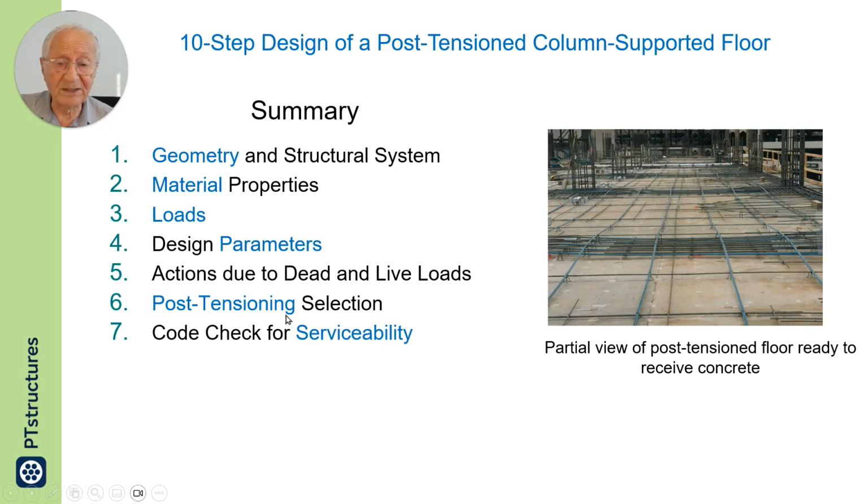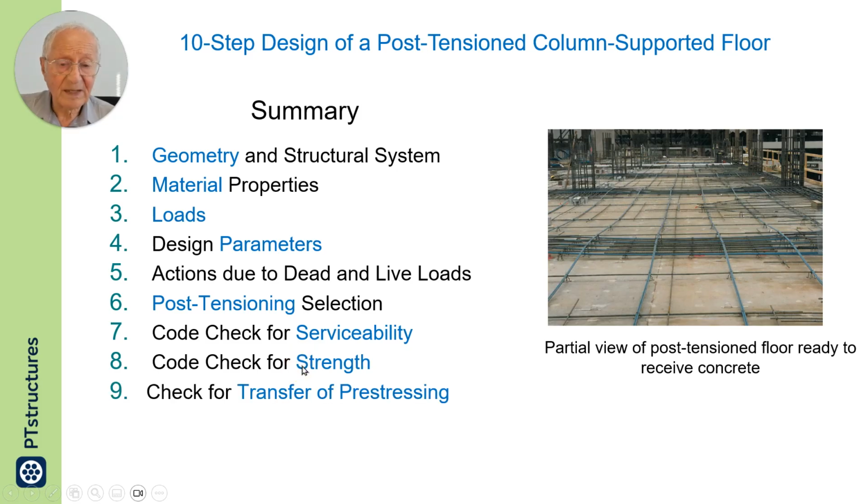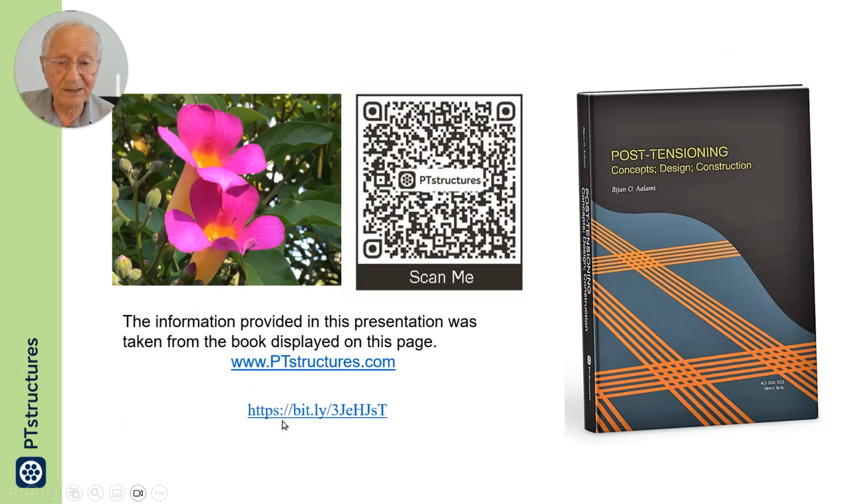We calculated the values from post-tensioning and did serviceability check. We moved to strength check and did also check for transfer of pre-stressing at time of stressing and did detailing.